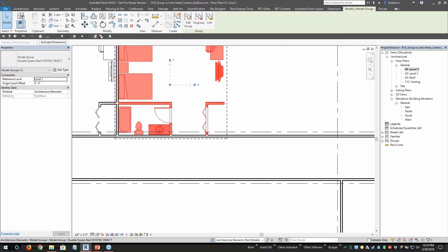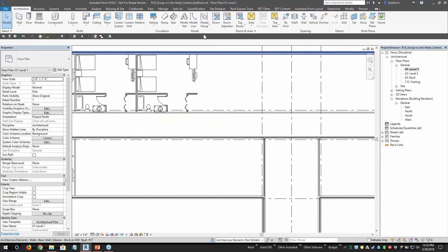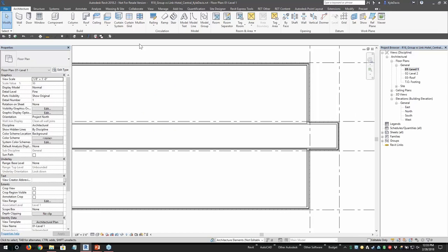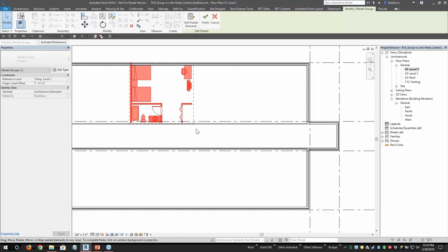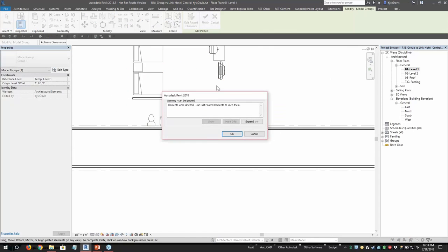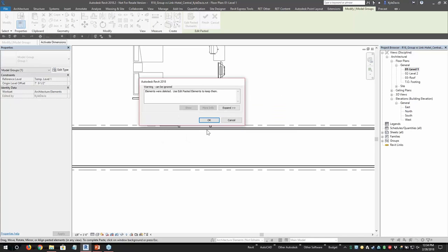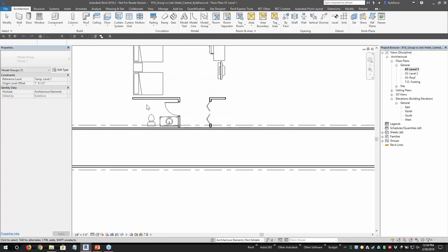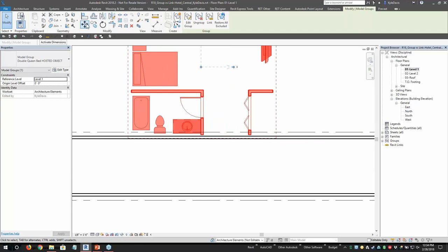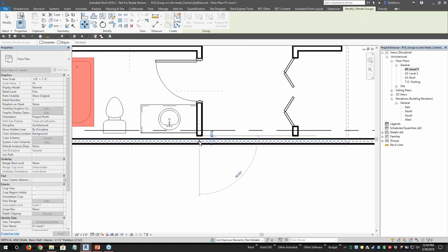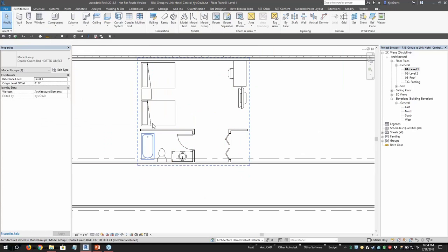And then if I take this group again, and let's say I'm placing this group somewhere else in the project. So I'm in another location, and I want to place that group. I'm going to place this group, pick that group, and place it right there. Elements were deleted. And that's really because of the tub. It was in the group. It's no longer able to host to anything. So I have to have an object there. So I'm going to move this down here to get those elements corrected.